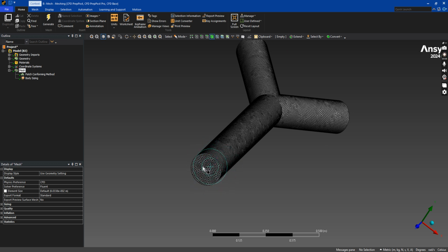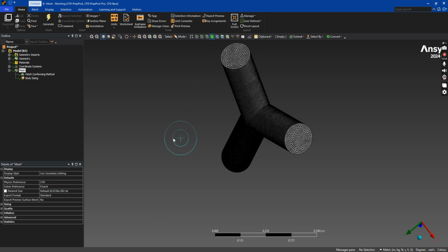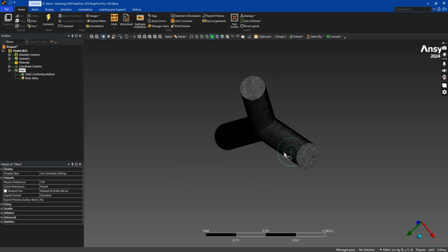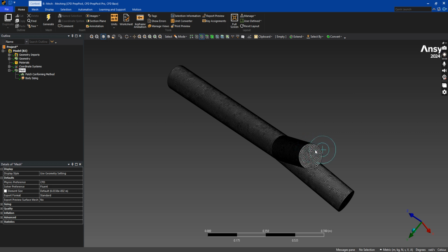this surface here will be acting as our inlet, and the other two surfaces here will be acting as our outlet. So as we have seen in the 90-degree bend pipe, the edges of the flow matter the most while meshing. As our flow will be entering here and going out from these parts, these edges of these shapes are very important. So this edge, I should be able to select the edge.